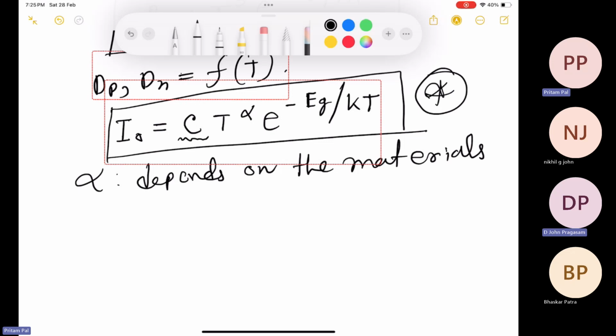But the question is diffusion current in a PN junction during forward bias is due to. I chose majority holes in the P side and majority electrons in the N side, but the answer is marked incorrect, and the correct answer is minority electrons in the P side and minority holes in the N side.